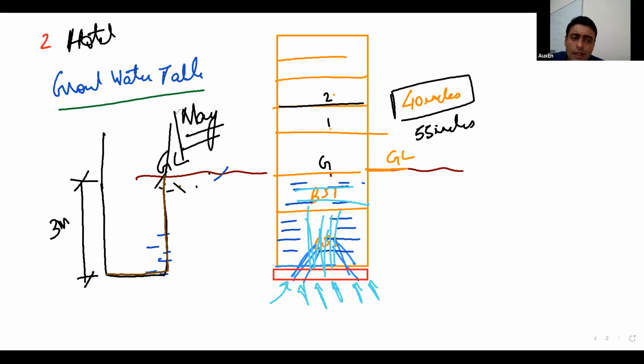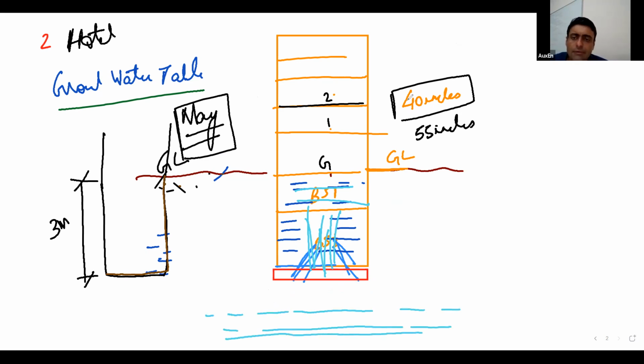So the geotechnical investigation was carried out in the month of May, and then what they had written in their report was that the groundwater table was, let us say, over here. I do not remember the exact values, I'm just writing some value over here. So they reported that the groundwater table was found 8 meters below the ground level. And your structure was only going to be constructed till, let us say, 7 meter or 6 meter below the ground level.